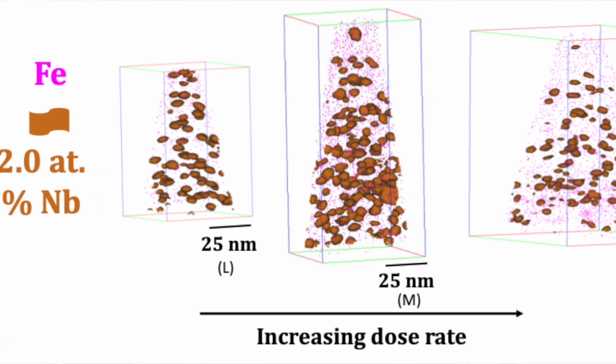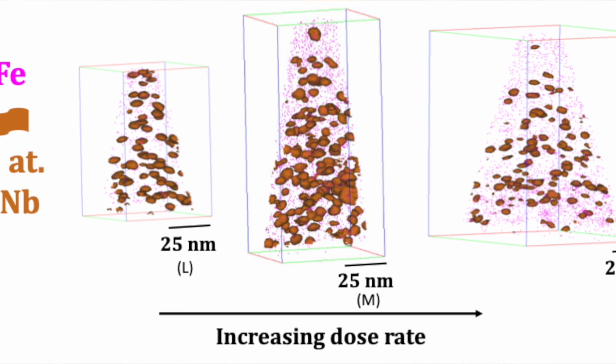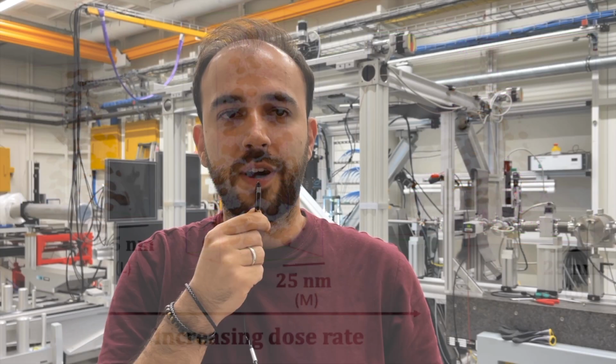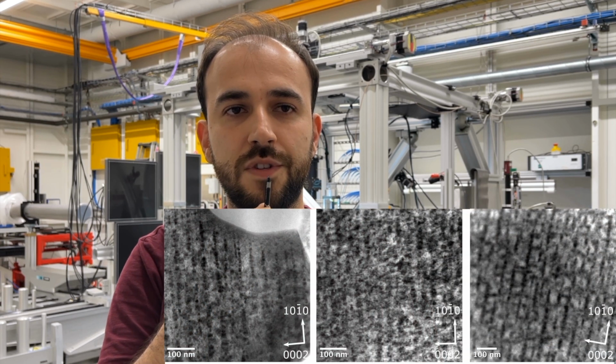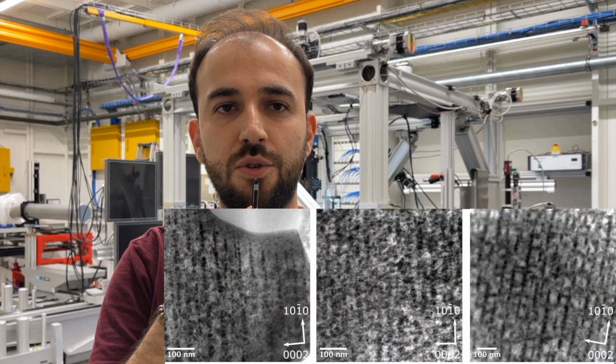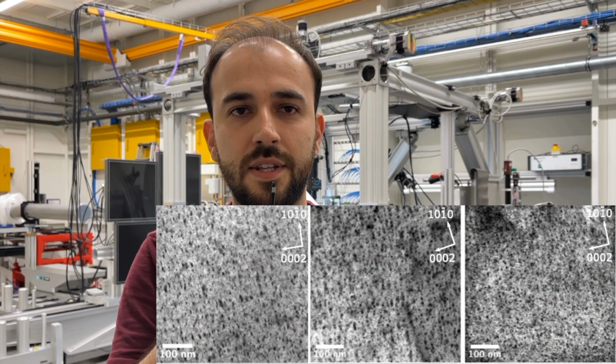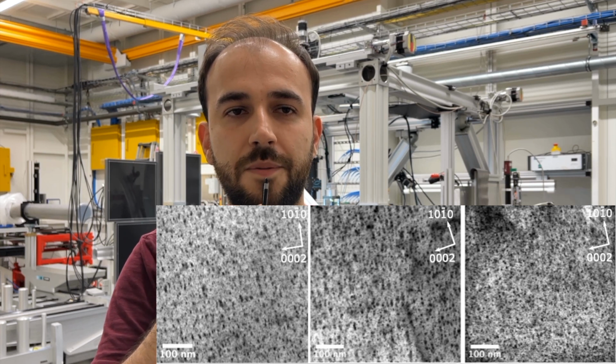Moreover, almost immediate niobium nanocluster formation was confirmed through APT experiments in Low-Tin ZIRLO, while dose rate increase seemed to result in smaller cluster size. The STEM investigations of the two alloys revealed significant a-loop alignment along the basal planes at this early damage level, while this was less pronounced in Low-Tin ZIRLO samples.